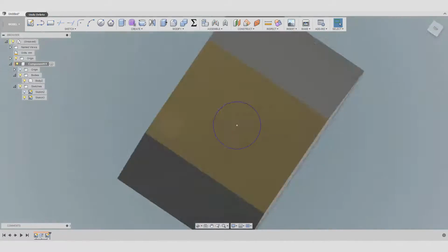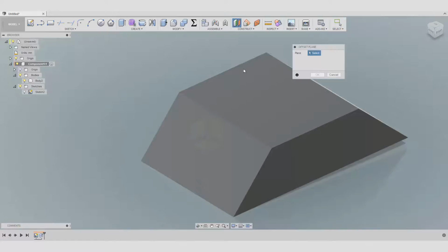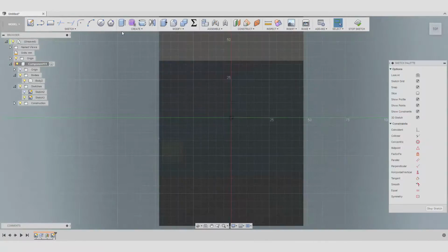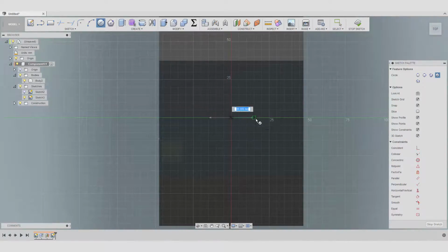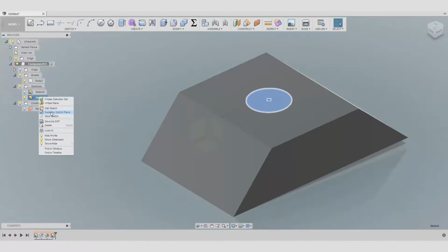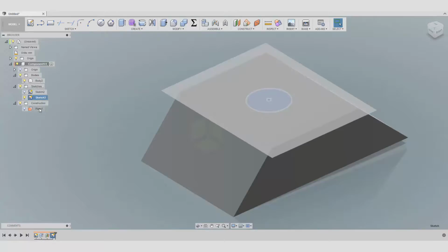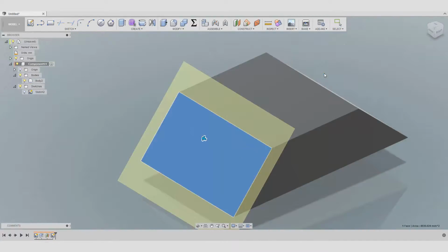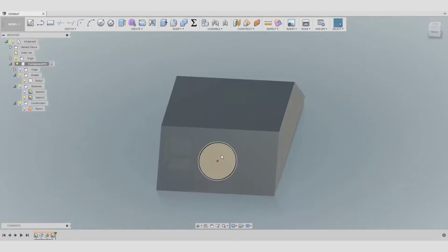If you created a plane before, yes, if you have a plane before you create the sketch, all you gotta do, let me show you. So we created the sketch on this new plane. All you gotta do is don't use the redefine sketch plane. Use the edit feature. And here you can choose, okay, I don't want it here, I want it actually here. Boom. And then it's gonna be repositioned also in the middle.